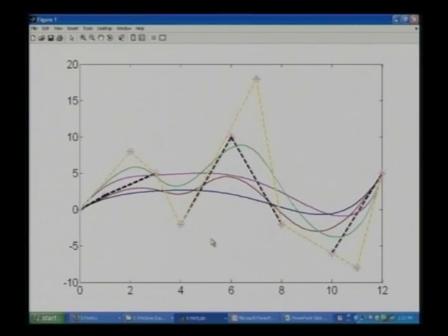Look at how closely the B-Spline curves follow the undulations reflected by the control points, or the control polyline for that matter. Why do you think this is possible? It is because of the strong convex hull property, or the strong local barycentricity that the B-Spline basis functions have to offer.